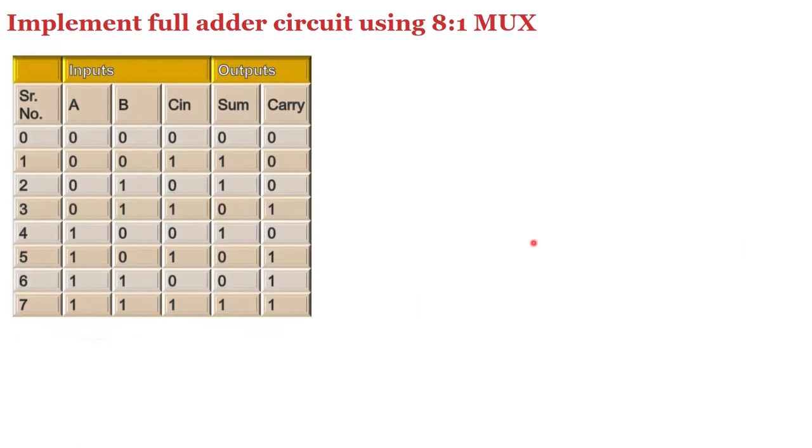Imagine you have the same truth table of the full adder. Again, you have A, B, C, three inputs. There are a total of 8 possible combinations from 0, 0, 0 up to 1, 1, 1. You have two columns, sum and carry. But now instead of marking min terms to be true, we are marking min terms to be false.